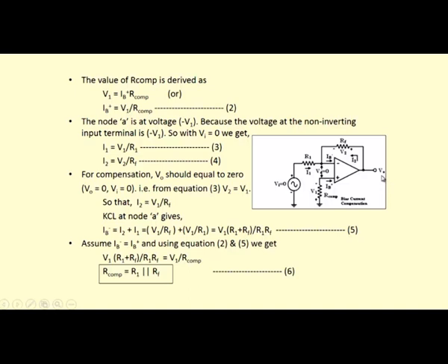If you use this, then the voltage produced by the bias current will be equal to 0. So, the bias current compensation is done by using the R compensation resistance between the positive terminal of IC 741 and ground. The next parameter is input offset current. We have used the R compensation, so the effect of the bias current is nullified, and the input offset current is nothing but the difference between the bias currents.